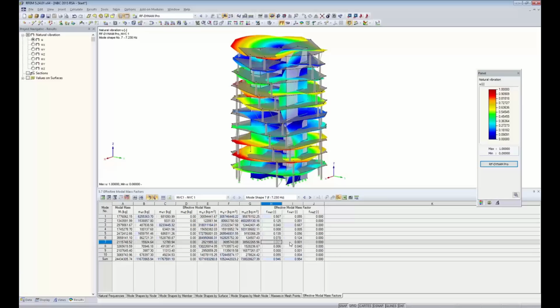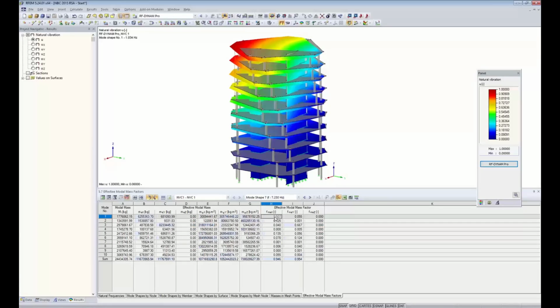And in that scenario, maybe we need to consider how our mass is distributed, and maybe we use some of those options I showed you before where we manually define some masses at nodes and at lines and so on. So definitely don't want to have a whole lot of local modes. Instead, we like to see at least one dominant mode, of course, in each direction as well.